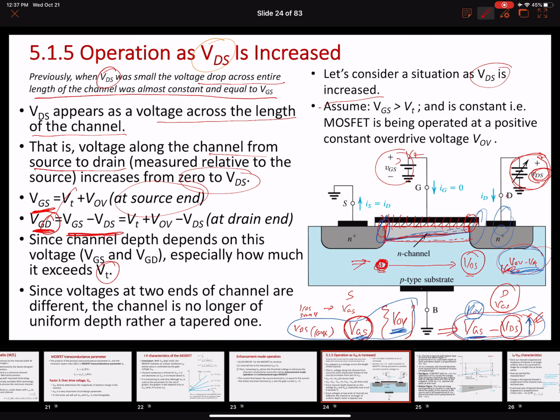Then we discussed what will happen when we further increase the VDS and it can no longer be ignored. At the source end, we have the overdrive voltage, and at the drain end, we have VGS minus VDS. Our channel becomes tapered rather than a uniform rectangle.